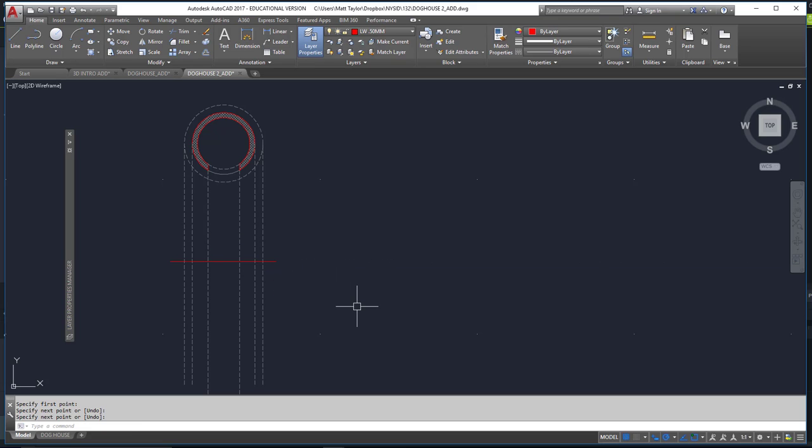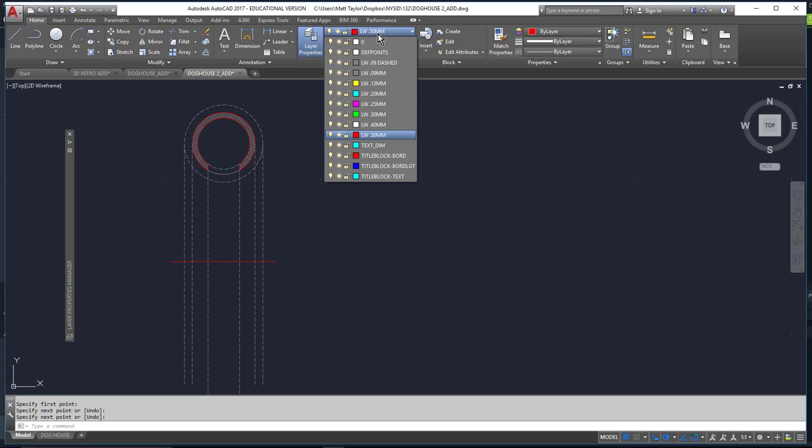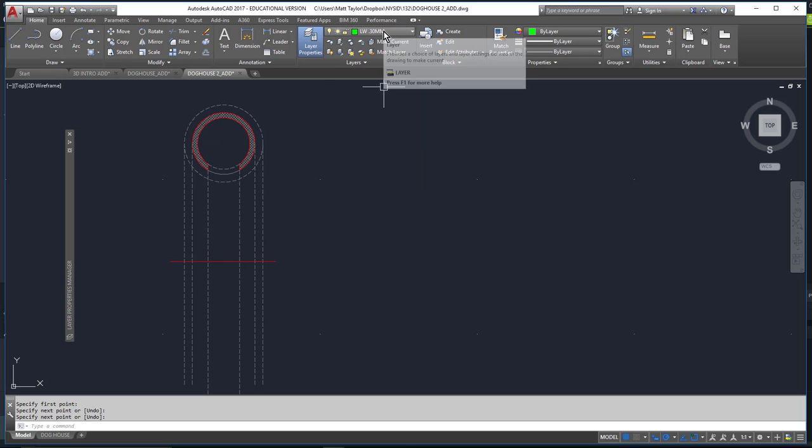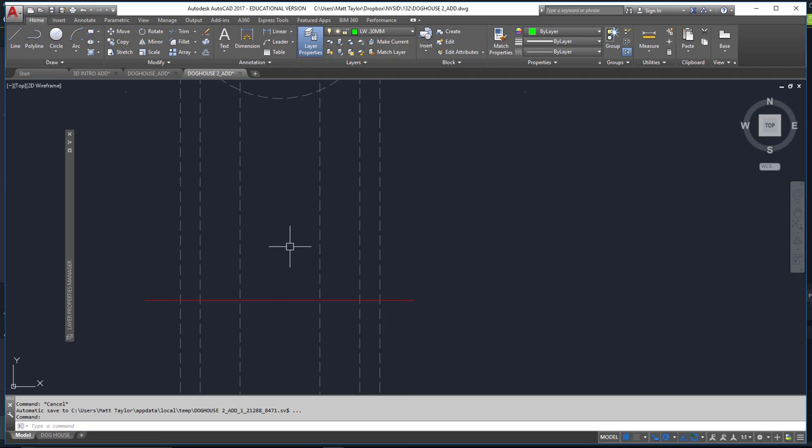All right. Now, since this is an elevation, the rest of it, I'm going to go slightly narrower, or the line weight will be slightly lighter, so I'm going to use line weight 0.3. Let's see, the bottom part of the doghouse is a cylinder. It's a concrete cylinder, and then it's topped with a sheet metal conical roof.